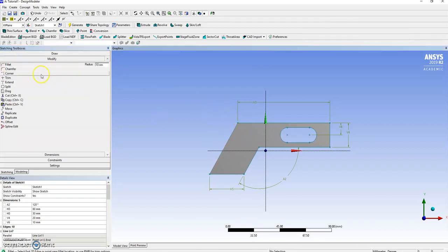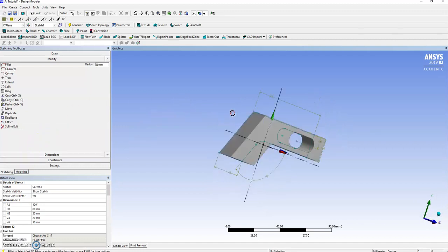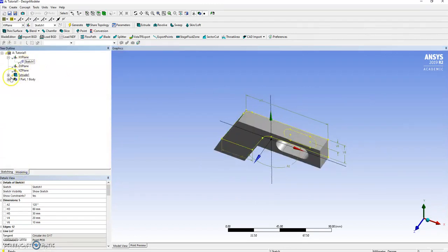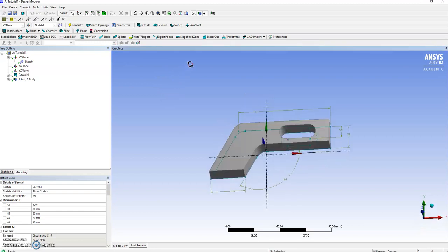I'll use that. So you select on fillet mode. 1, 2, filleted. 1, 2, filleted. Now, fantastic. Yeah, it hasn't done it. No, why? The usual trick. I need to generate my extrude. Again, regenerate. It should do it by itself, it was smart, but it's an oldish software. Okay, great, it has been filleted.